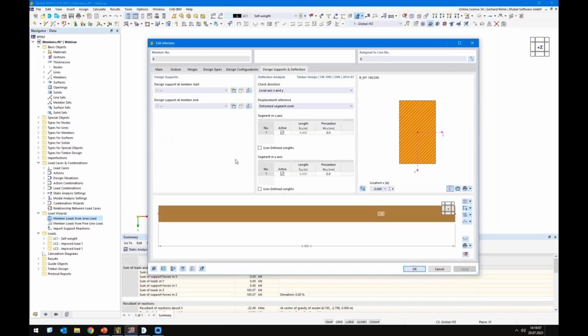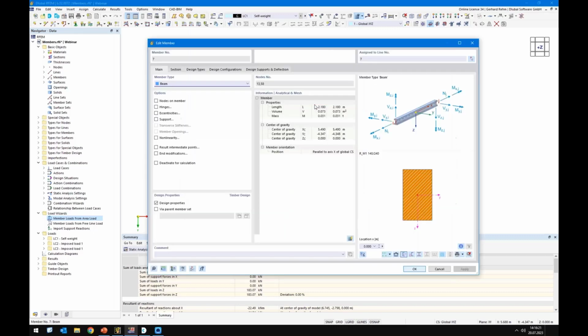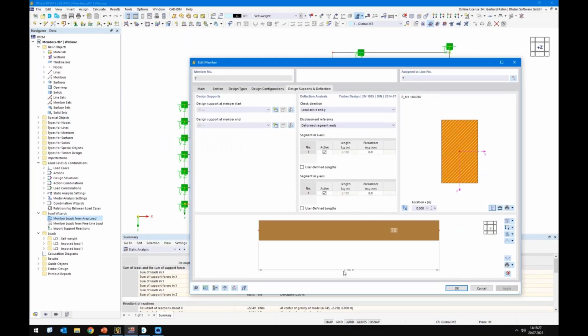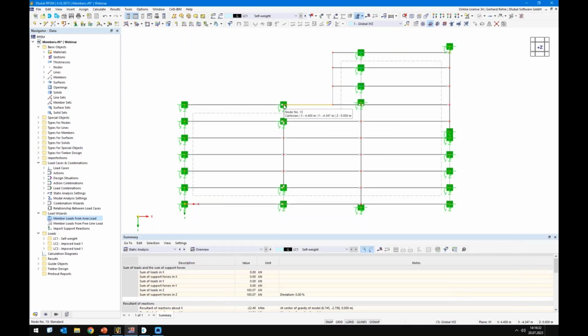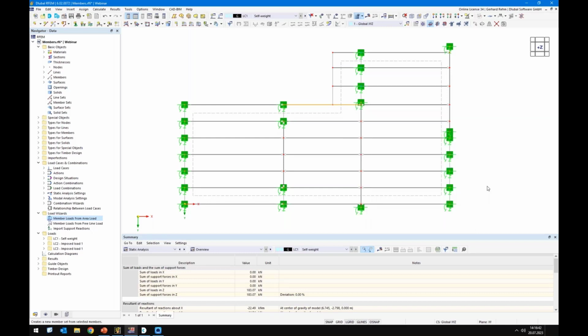So that means I don't have to do anything for the floor beams, but for the downstand beams and also for these beams here and for the cantilever. Because right now, if I would design it as a member for this beam here, I would get a reference length of 2.18 m, which is of course not wished. We should use a reference length for the SLS design of, in this case, 3.44 m. This we do by combining these two members using a member set.